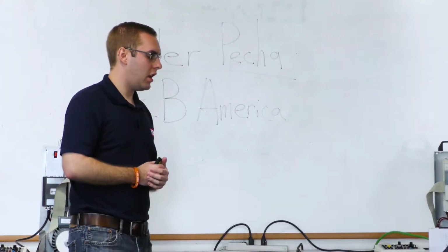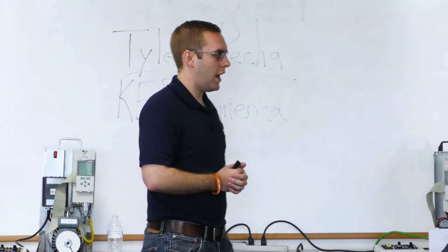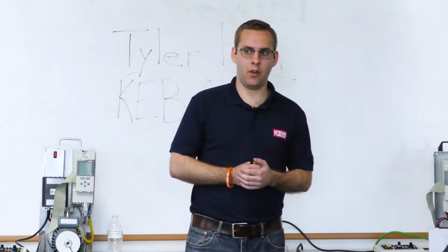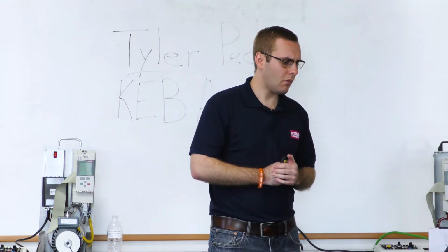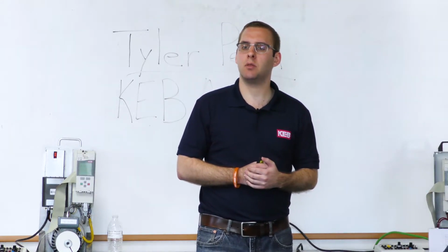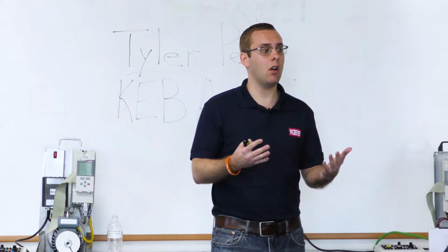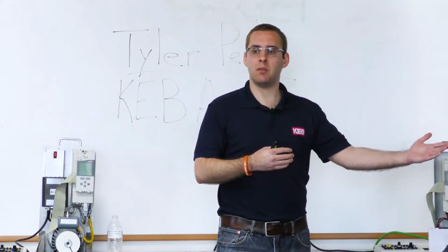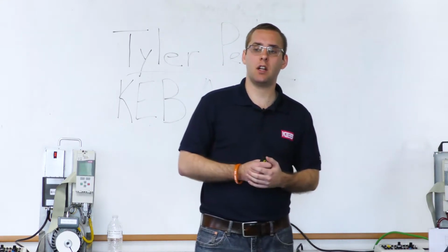As a note, the 460 volt drives can be used on single phase 230, but we need to program an input for that. If you are using a battery backup system and you'd like to use this function, the input needs to be programmed for that. We'll talk about that in the input section, but if you're getting this error when you're switching over to emergency power, if you don't have your input set correctly, that could also be the cause of this.